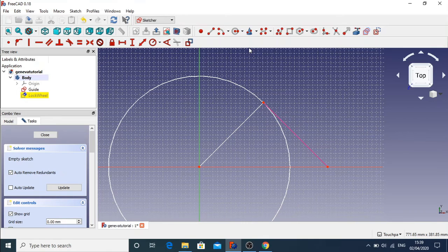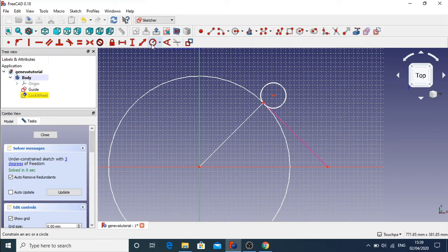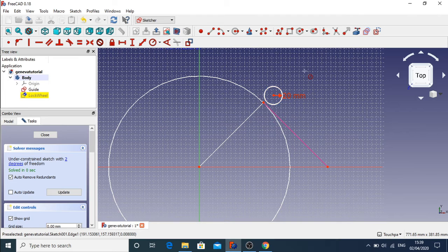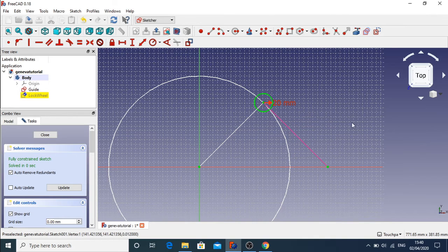So escape to get your cursor back, click on the create a circle, and we're going to create a 20mm circle, and using our arc constraint, constraint to 20mm, press escape, and then I'm going to move this into place, and because I've imported this edge, I'll get these points in as well, so I can actually click on these 2 points, circle and the external guide geometry, and constrain those up.